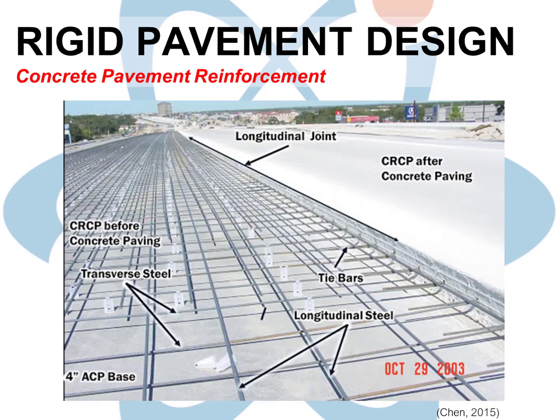You might be thinking, why don't we just put in a bunch of reinforcing steel into the concrete and avoid a lot of problems? One advantage of heavy steel reinforcement is that joints can be placed at dramatically greater intervals, and damage to the roads due to poorly performing joints isn't really much of a thing. We can do that, and we have done that, and we now know that reinforced pavements are not always a good answer.